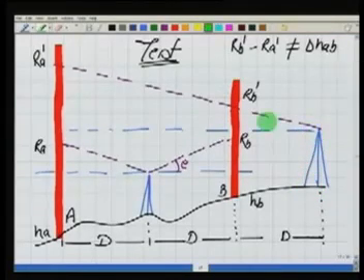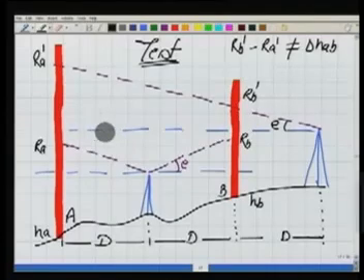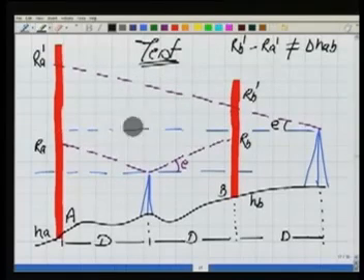Now from here, I take the observation, and if I sight, again I will have the error E. In the ideal case, I should have looked in the horizontal direction here. In the ideal case, this is the direction, but because of the error, I am looking in this direction, and I am bisecting, and I am observing the values RB dash and RA dash. This is what I am observing.